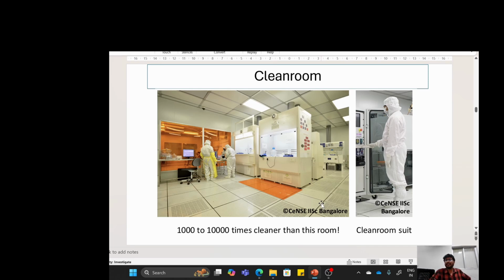It will kill your device, because the diffusion of sodium is too fast, and it will go all inside your silicon wafer. That will kill all your devices. So that is why cleanliness matters, mainly particle contamination, because if a dust particle sits there, it will contaminate your wafer.